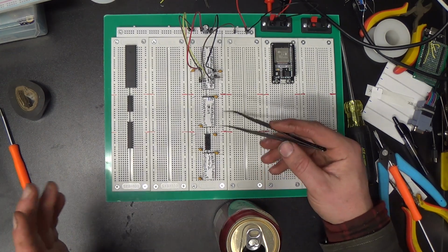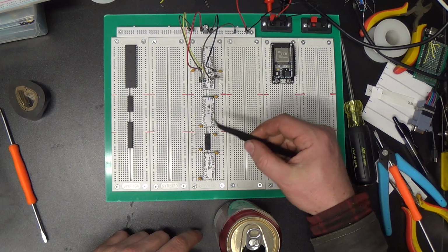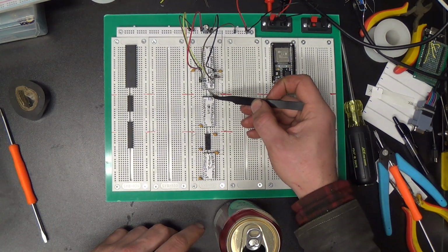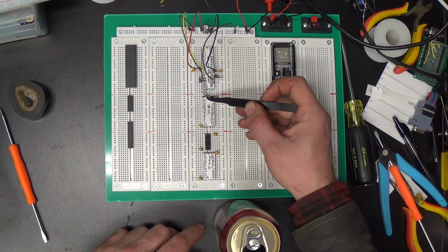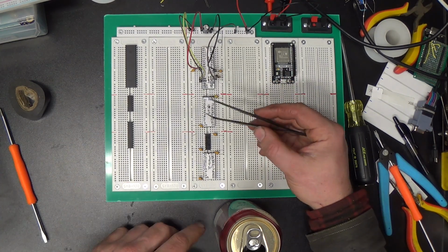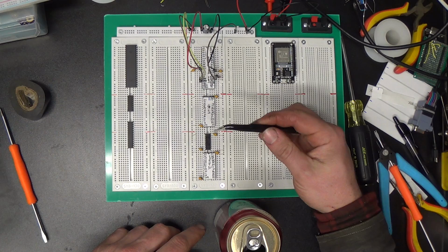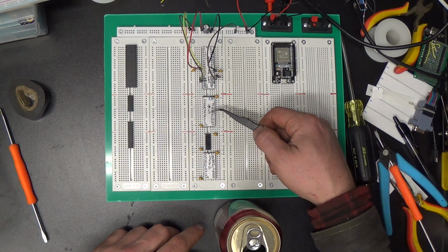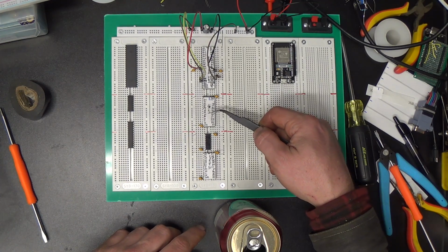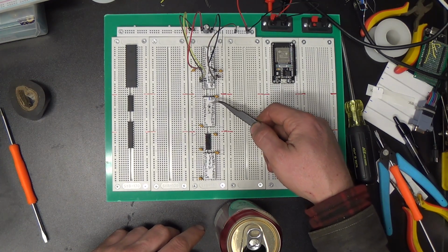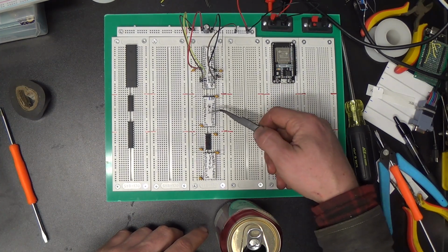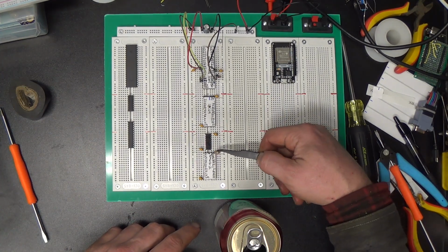So, the plan here is to just write some simple software and burn it to the ROM that just makes some I/O requests so we can see that everything's working. And technically, we could probably do that without any RAM. We could just write some Z80 assembler, and assemble it and burn it to the ROM and just do everything in registers and not fool around with needing this RAM.